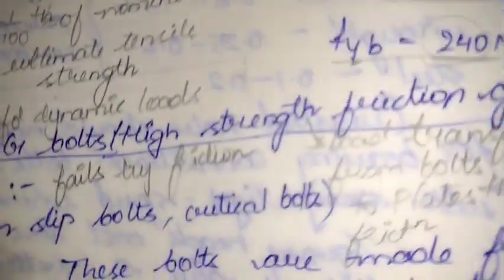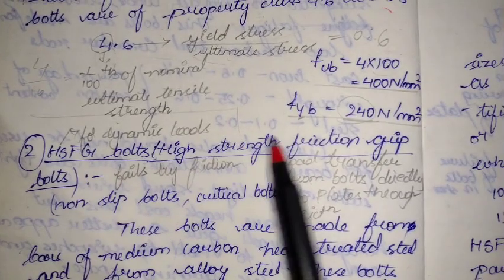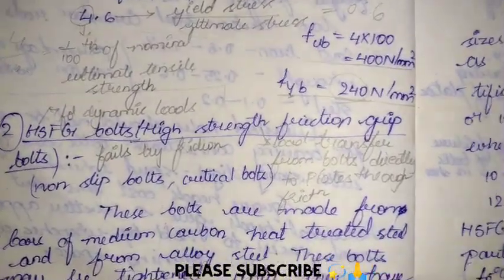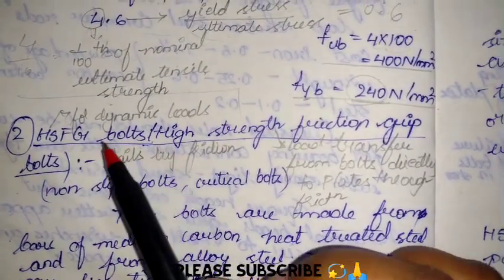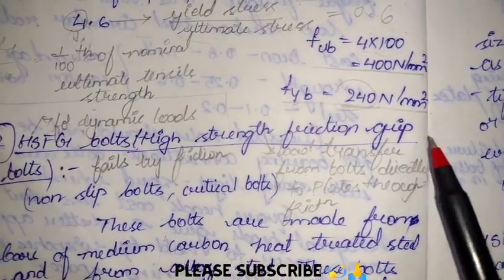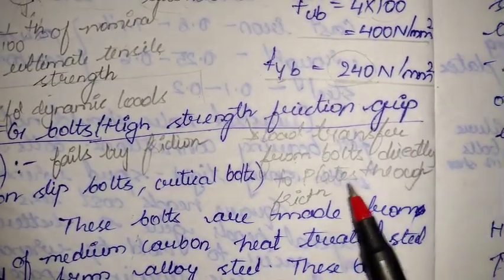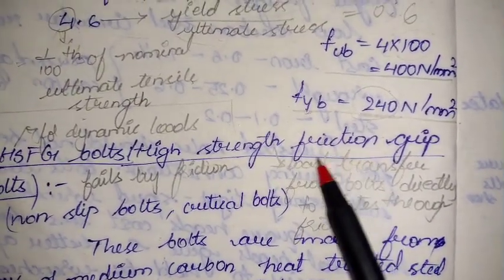Okay. Next we have the second type of bolt, that is HSFG, the high strength friction grip bolt. The first one is the ordinary bolt, the non-friction type bolt, the slip type bolt. But the second one is the HSFG bolt. HSFG is high strength friction grip, and these are used for dynamic loads. They fail by friction. Here the load transfers from bolts directly to plates through friction. So the load transfer mechanism is friction.